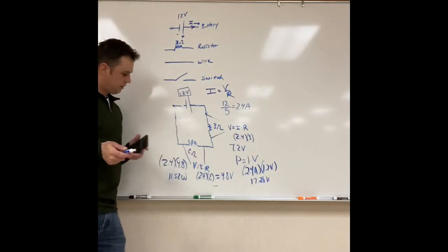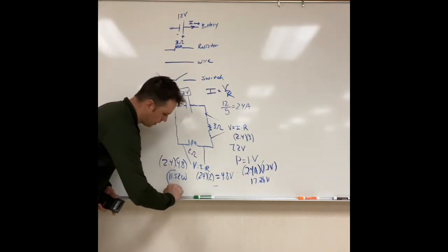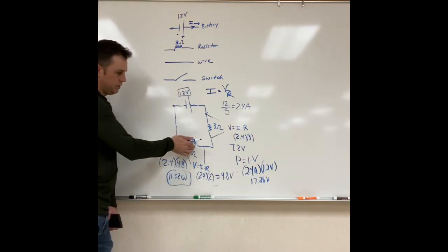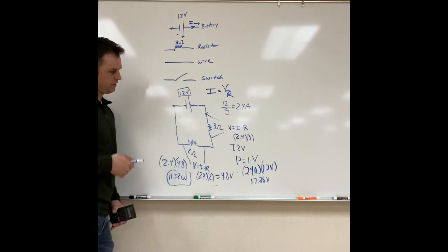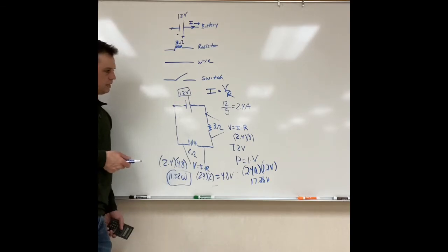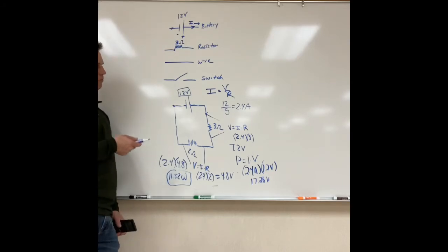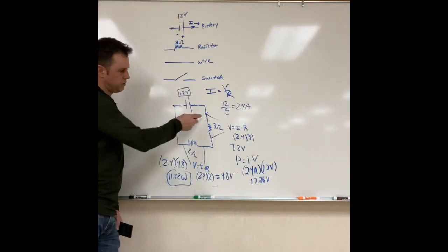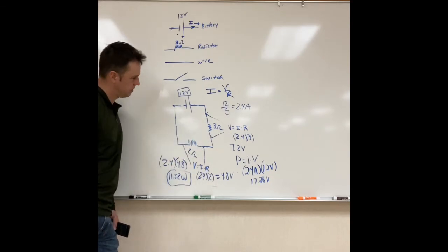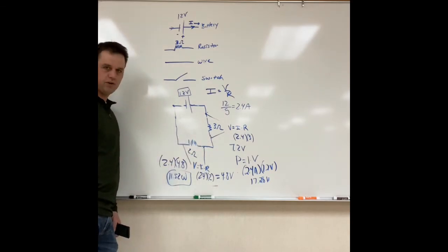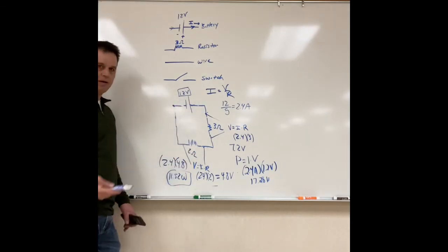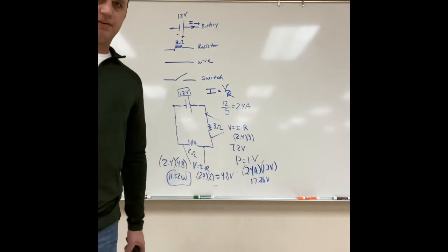Right, so these wattages are the rate at which these resistors are converting energy from electrical into some other form. Right? It's important that you realize that voltage is across devices. So there's a 7.2 volt drop across this resistor and a 2.4 volt drop across that resistor. Voltage doesn't flow. It's not like voltage leaves the battery. Current leaves the battery. Voltage is across devices.